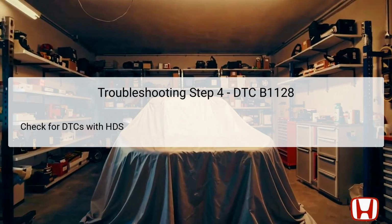After testing the driver's door lock switch, the next step is to check if the DTC B1128 is indicated again using the Honda Diagnostic System, HDS. Connecting the diagnostic tool allows you to read the current fault codes present in the system. If DTC B1128 appears once more, it indicates that the issue has not resolved and further diagnostic steps are necessary.